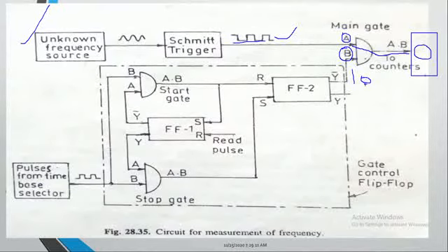If one of the inputs of the AND gate is 0, then the output is 0. If one of the inputs of the AND gate is 1, then the output is nothing but the other input, which is A, and these pulses are fed as an input to the counter. Okay, so just remember that. Now coming to the rest of the blocks. As I told you, this is acting as a switch, and to this particular switch we should apply 1 as well as 0. Whenever we make this B input 1, at that time the counter is counting the number of pulses.